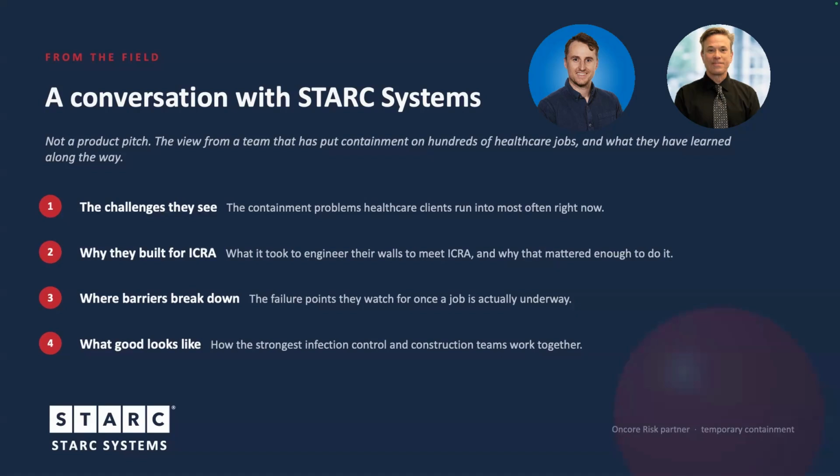When you have a fully sprinklered area in the construction area as well as outside, you have the ceiling tile and then you have a sprinkler head, obviously. And as I mentioned earlier, we don't ever sprinkler above the ceiling because that ceiling tile provides some rating as well. And so when you take the ceiling tile out, you can't just leave the sprinkler heads down. That doesn't meet any requirement for fully sprinklered space.